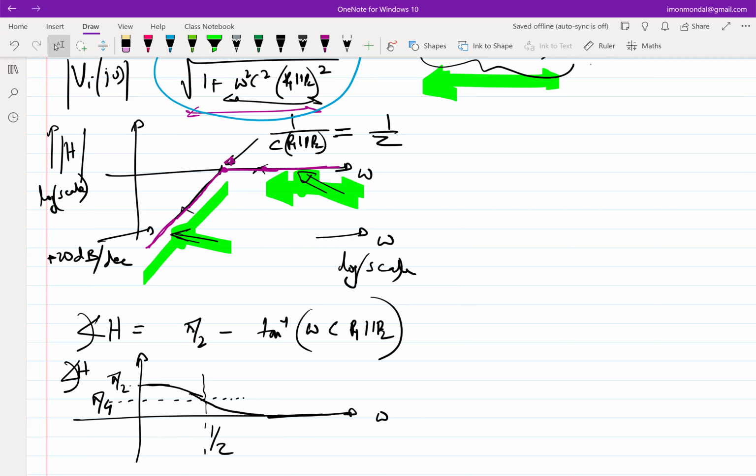We will know the phase response as long as we know the magnitude response, because the way the poles and zeros affect your magnitude response, they also affect the phase response in a certain known manner. We'll deal with this in more detail later on, but this is just a preface.